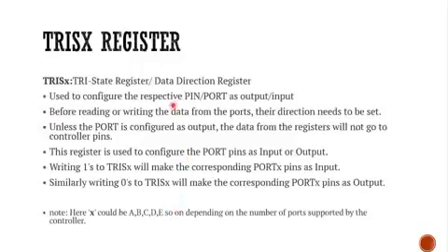So what is TRISX? TRISX is actually a tri-state register or data direction register. We use it to configure a specific port. Let's say when you want to use port A, we need to refer to TRISA. X here will become A. If we want to refer to port C, then TRISX here will become C.